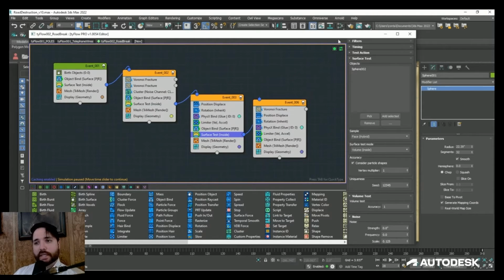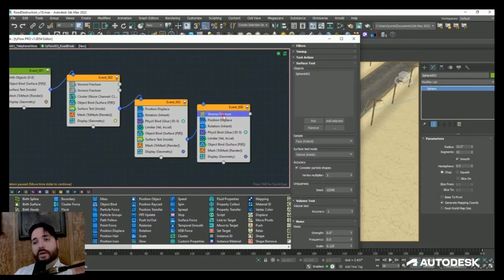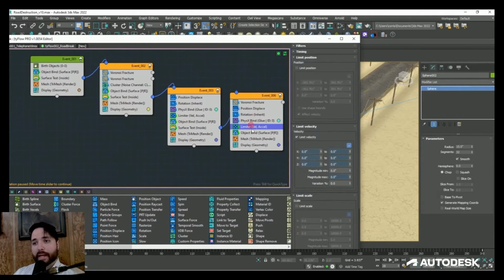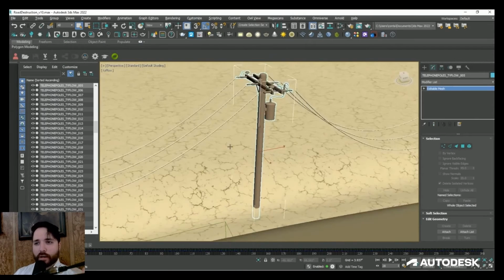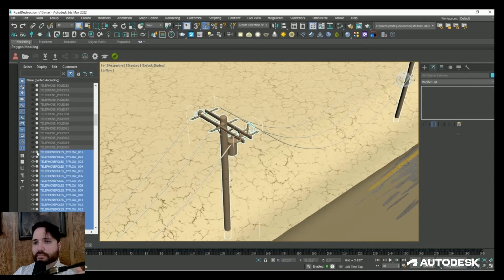The smaller secondary sphere collider was trailing slightly behind the larger sphere object, and it was used to trigger the fourth TyFlow event, where the road chunks were fractured for a second time. And I also made sure to include the position and rotation operators as well in order to help to displace the particles and make the asphalt look like it was cracking as soon as the particles entered that event.